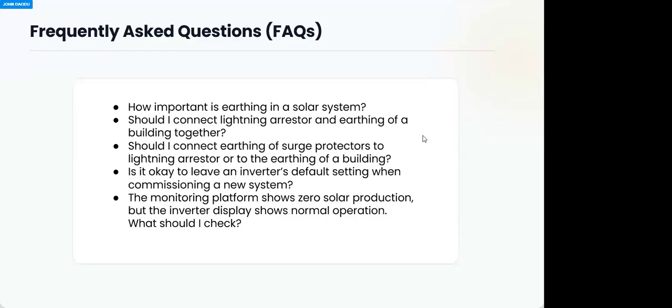But the main charging current of the battery from the charge controller, if you establish that that is working well, you should be able to see it when you press some buttons on the charge controller. You scroll to where you will see it, if it's not displaying it on the default screen. You press a button to set for it.